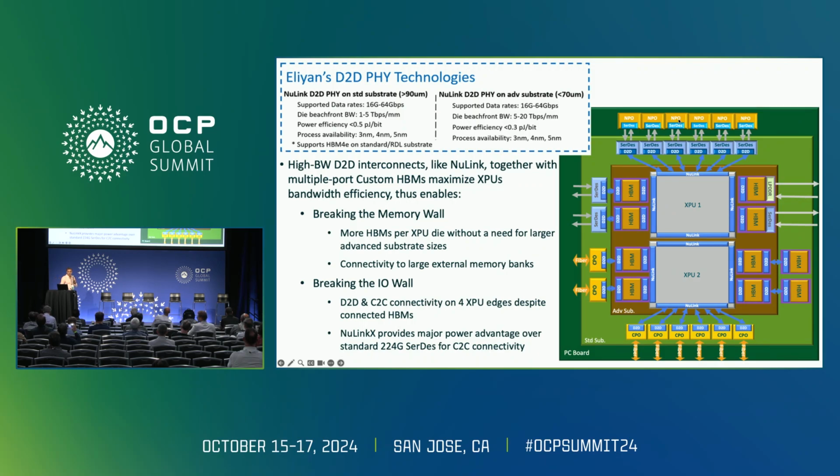Or usually today, when you put this HBM across one edge of a processor, effectively this edge is not usable anymore. It's a waste. But given that you can get a lot of bandwidth through that beachfront, you can pass the excess bandwidth to the other side and use it for SerDes communication externally.